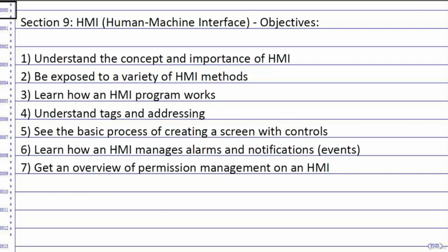Speaking of tags, addressing those to different PLCs, understanding the idea of a B and an N and an F value, bits and integers and floats, by this point should certainly be no mystery. You should have a clear understanding of what those are and how to bring them into the HMI. Some HMIs, including the one that we used today, also have the option of limiting the operator input to within a certain range. That's very helpful in protecting the PLC program from erroneous entries.